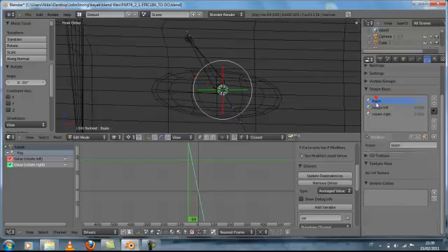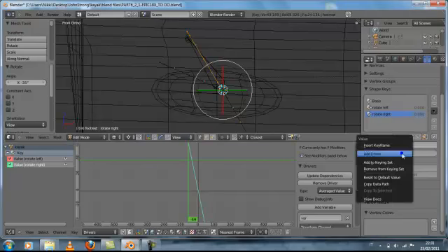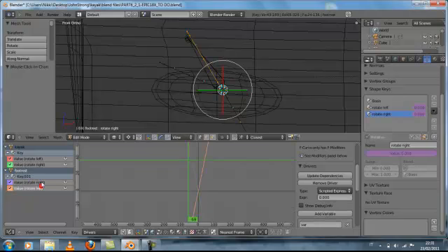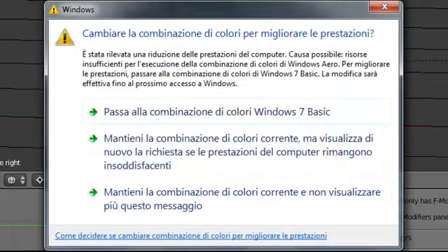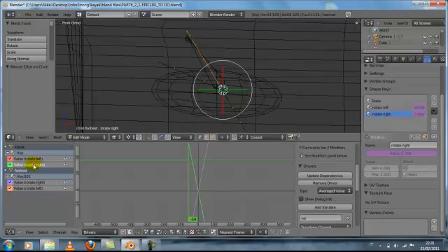Now, as you can see, we have created 3 shape keys. Okay, and now add the driver, right click of the mouse, and so here we have these 2 drivers. So for these 2 drivers, we have to set the same parameters of the rudder. Okay, and so rotate right value, so the right value and left value.